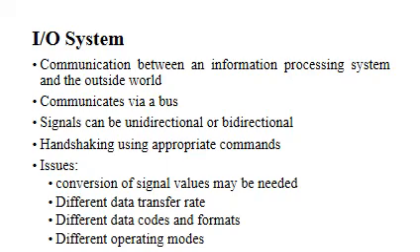Peripherals connected to a computer need special communication links for interfacing them with a central processing unit. Typically, a CPU communicates with input-output devices via a bus. The interface must have the necessary logic to interpret the device address generated by the processor. Handshaking should be implemented by the interface using appropriate commands like busy, ready, and wait, and the processor can communicate with an input-output device through the interface.